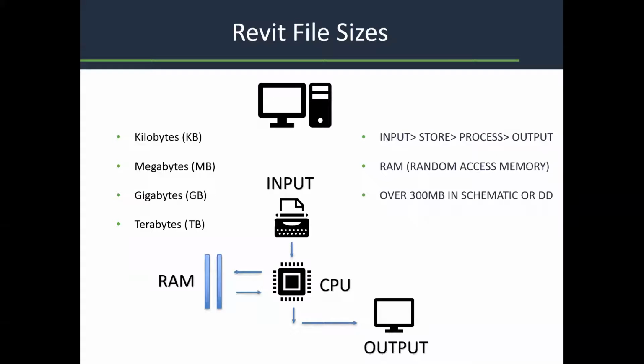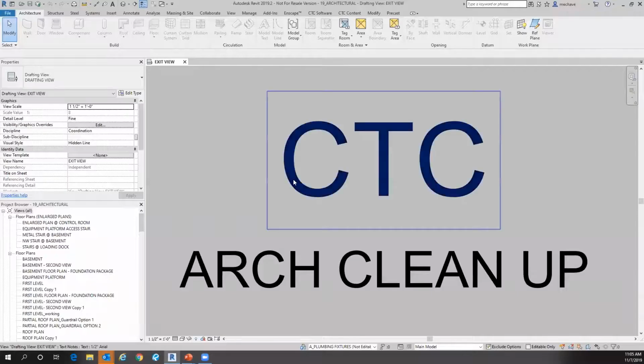If you see your file grow rapidly in size, you might want to leverage the Project Cleaner to do a lightweight cleanup, or some of the CTC tools in the data suite that will give you a more analytical breakdown of your model. For now, we are going to use the Project Cleaner and reference the file size itself. And of course, I don't believe in death by PowerPoint. So now we're going to go into Revit and talk about the Project Cleaner itself.